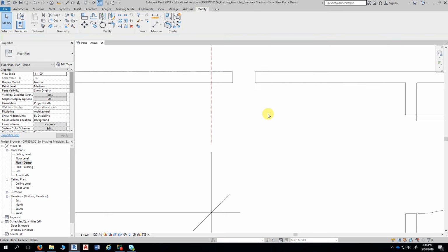So having unlocked the gap, we can now take each of these wall ends to the reference plane. And we do that how? Click on the blue spot. Sorry? Clicking on the blue spot? No, more accurately than that. Align. Okay. You can also drag it, but that won't be accurate. No dragging. All right. Dragging's a bit hit and miss, so we have to be certain. So, if it's mission critical, align.